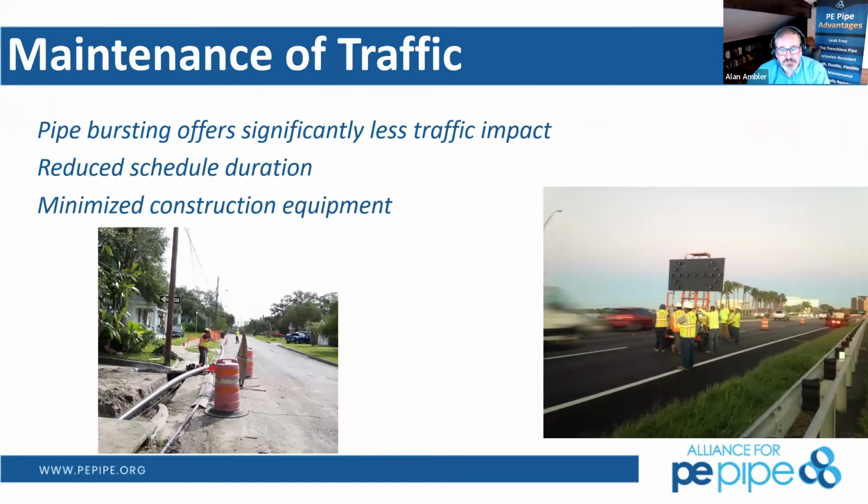We do have to look at maintenance of traffic. So in some instances and areas, the actual activity of moving the maintenance of traffic into travelways can eat up quite a bit of your production time. As you see here in this Courtney Campbell Causeway project in the bottom right, it took 2 hours of a 10-hour closure to move equipment onto and off of a pipe bursting road as we went through this project.